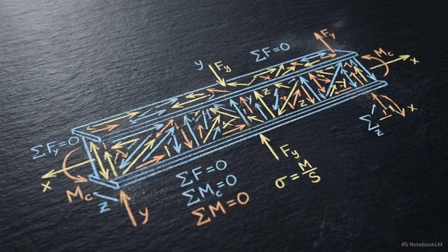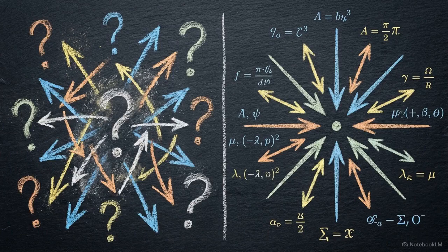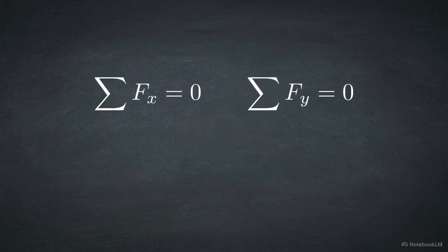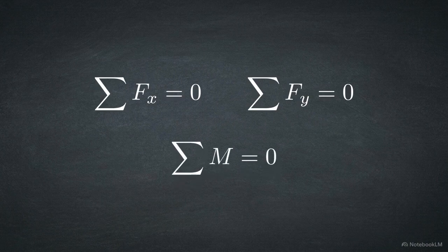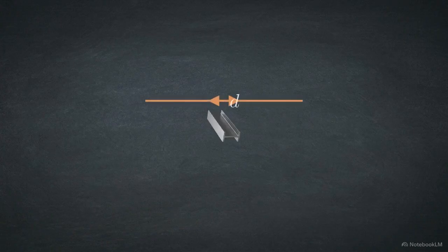Once the free body diagram is drawn, the physical object ceases to exist. The physical forces are now a problem of pure geometry and algebra. With the unknowns exposed, we apply the laws of static equilibrium to solve them. Mathematically, this means the sum of all linear forces must equal 0, and the sum of all rotational moments must equal 0. In a concurrent force system, all vectors intersect at a single point, meaning no rotation can occur. But in a non-concurrent system, forces apply leverage across a distance.